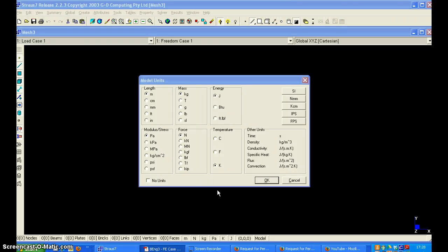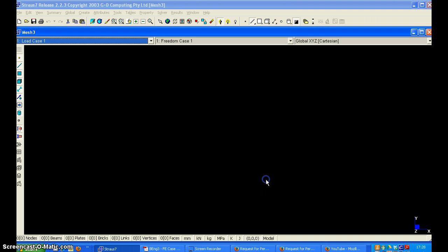In this example, a cantilevered beam will be modeled using the plane stress surface, using membrane elements. So the 3D structure will be modeled as a vertical plate parallel to the direction of the load. We are again choosing the same units as in the previous example: megapascal, kilonewton, millimeters.